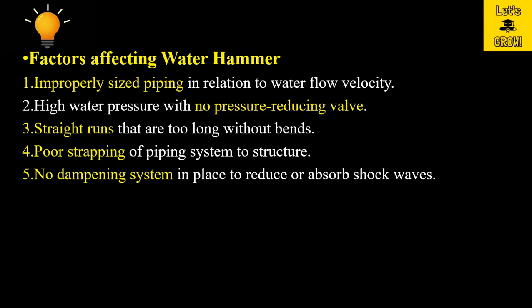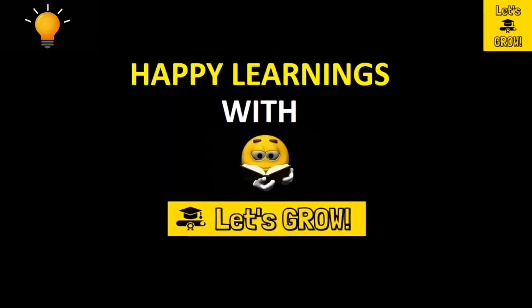Poor strapping of the piping system to the structure. If there is poor strapping, there are higher chances of cracking of the pipe at those particular points. No dampening system in place to reduce or absorb the shock wave. Some damping systems need to be placed to absorb these shock waves to reduce the water hammer effect.